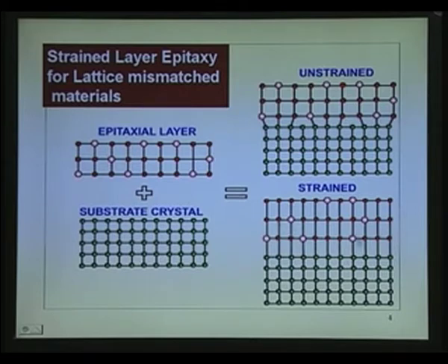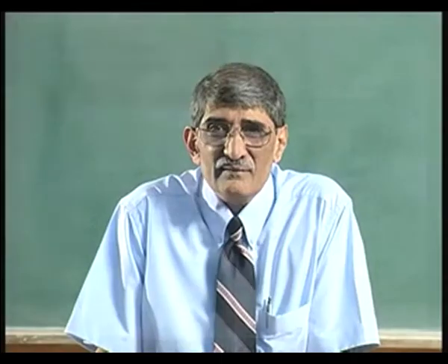And it has the mobilities which are high. In fact, this has peculiar properties which sometimes give even higher mobilities than the unstrained layer. But if you keep on growing thicker and thicker layers, then this pulls back to its original size, its minimum energy position, and the lattice breaks here. That is a defective layer here. So, once this was realized, people said, why not make devices like this?